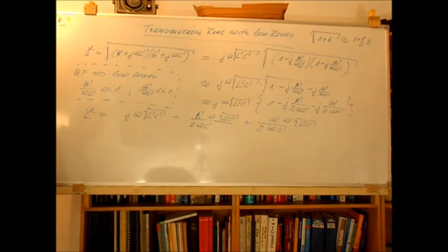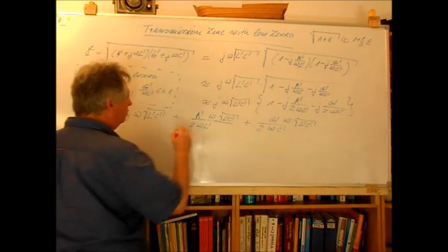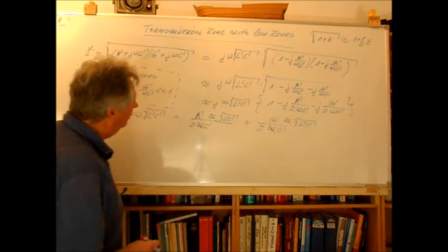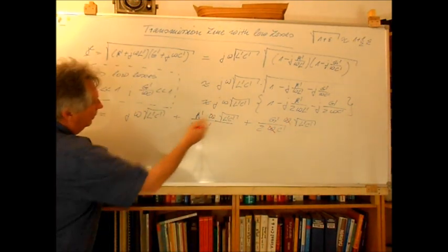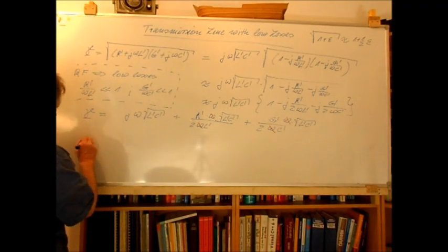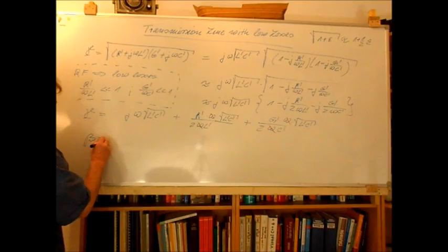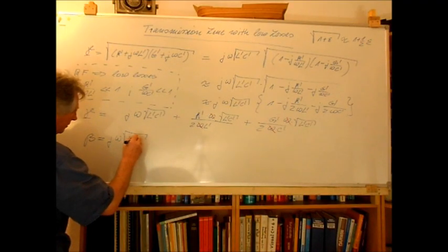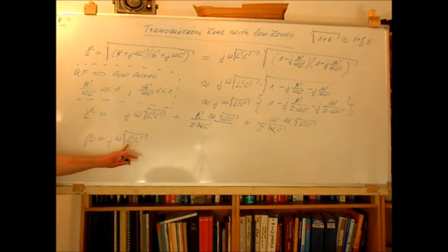And in this expression, of course, this will cancel against this, and we can also cancel L prime here. And you see here we have two parts, one imaginary part and one real part. The imaginary part will be beta, which we already know, is omega times the square root of L prime C prime, according to our transmission line system.